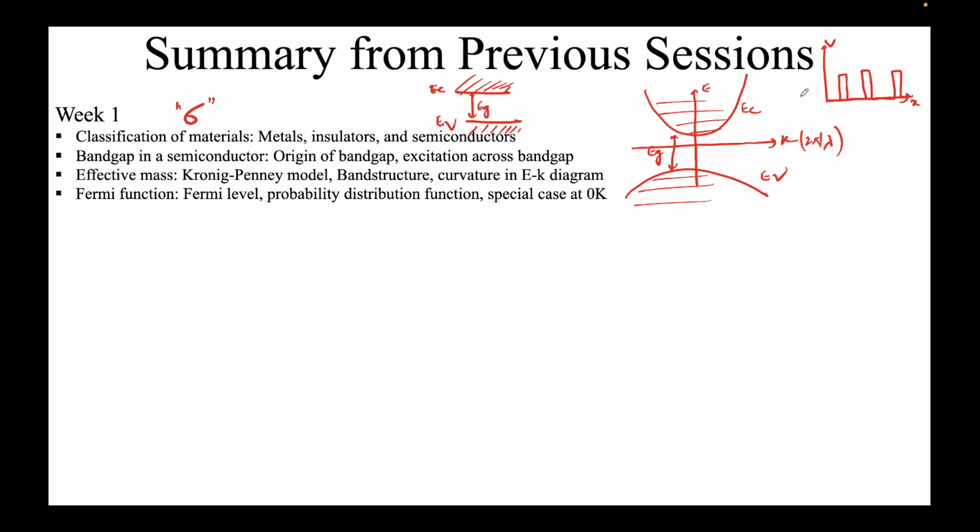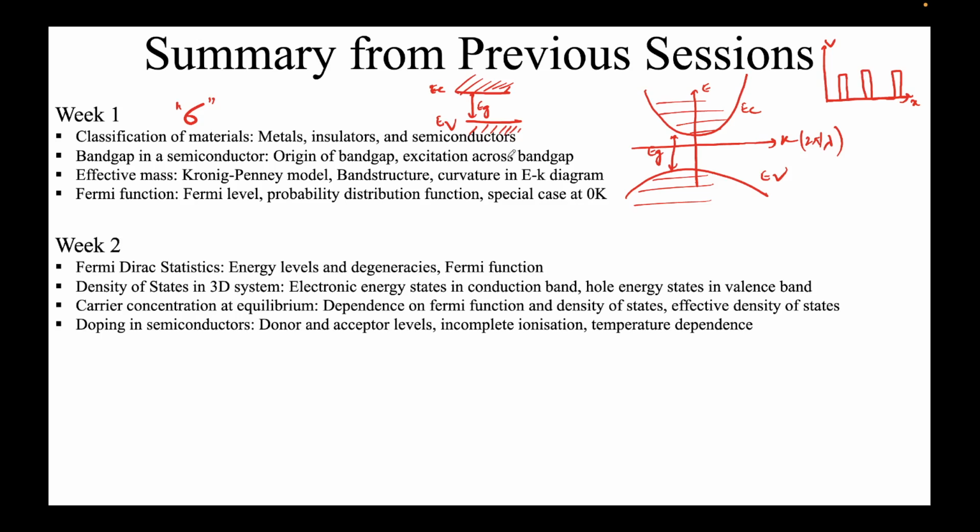The effective mass, as you can predict, depends on the periodic potential and other factors, which essentially depends on the nature of the material, the nature of the semiconductor that we are talking about. Finally, as I mentioned, we have these energy states which are over there, and we saw in a 3D system we defined an entity called the density of states, given by this symbol g(E).